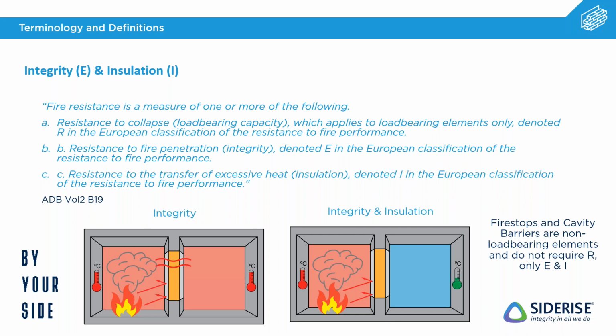A simple way of looking at integrity is, as I mentioned before, just its physical ability to block that fire from spreading. So taking that little diagram in the bottom left there, if you had two rooms next to each other and one fire in one of the rooms, but you had a hole in the adjoining wall, you could put a product in that hole or over the hole, and if it's got a good integrity, then it's going to stop that fire from spreading into that next room. And that's what integrity is all about. It's how long that product will physically stop that fire from spreading into that next compartment or room.